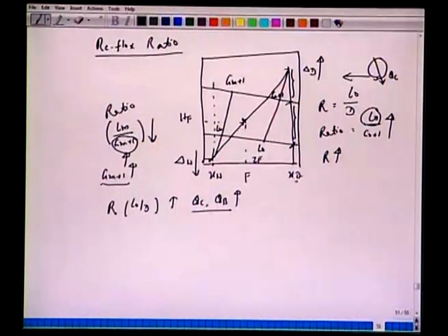So, as the load increases, keep F fixed and increase del D, the reflux ratio. In that case del W will also increase, which means Ln is increasing and Gn plus 1 is increasing, in which case we have QC and QB increasing here. Now, what happens to the number of trays?